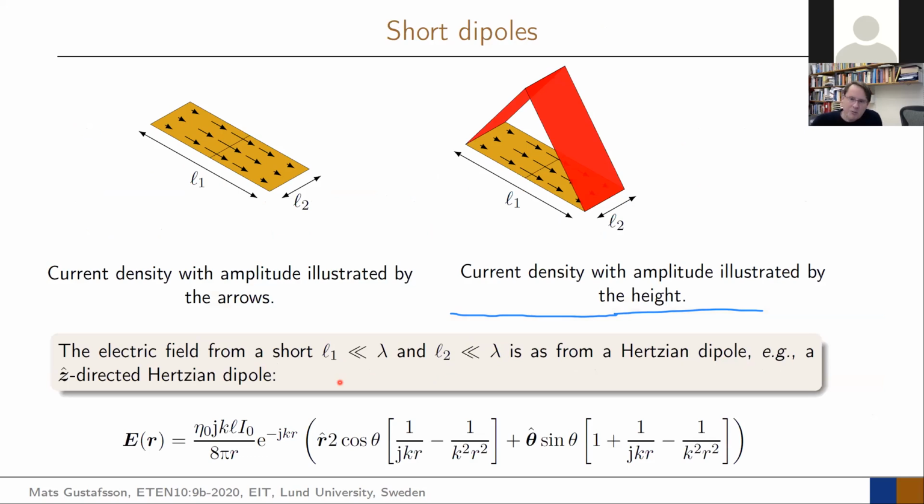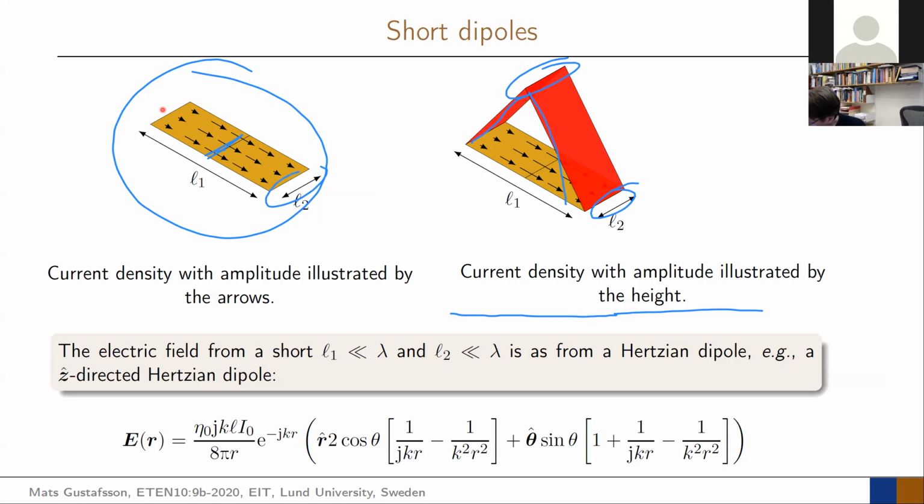So what we do is that we take our structure, we use these small dipoles here, so almost a Hertzian dipole, and we say that on these ones we have an approximation of the current as this rooftop function, so a triangular type function, high amplitude in the center, which we can see here, and 0 amplitude at the edges. And then we know if we had some current here, we have some amplitude of these ones.